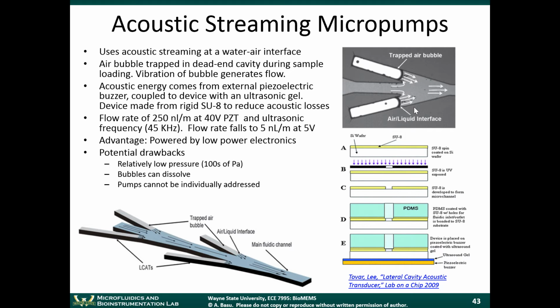This is a process flow on how that was made. So the buzzer is actually placed down here and the ultrasound gel is placed in the middle here. Notice that the piezoelectric device is just placed outside the chip rather than inside the chip. If you have microfabricated materials like PZT inside the chip, that would increase the cost. So by having the buzzer externally, it's more of a modular approach to doing this.